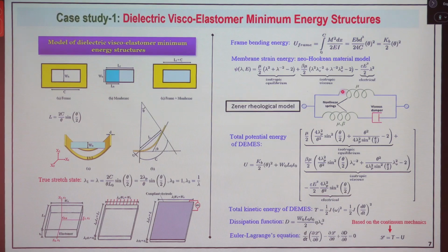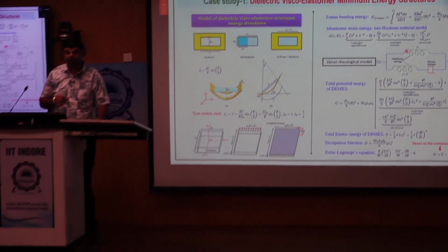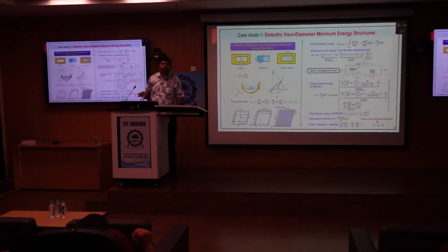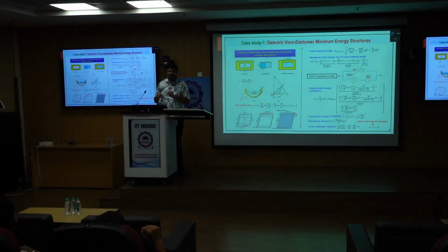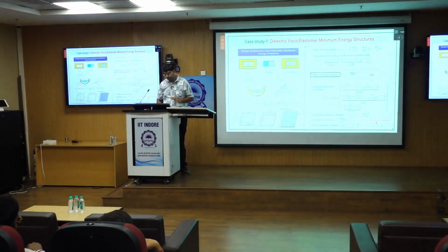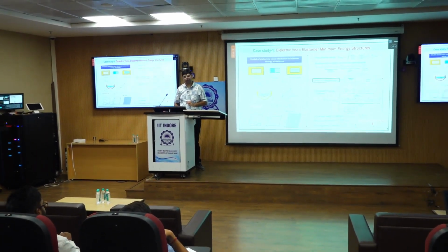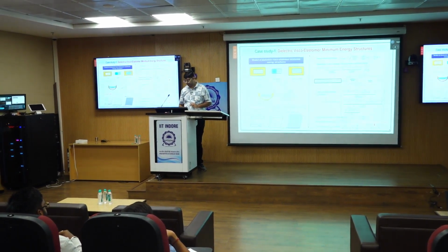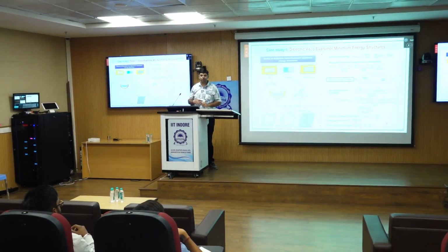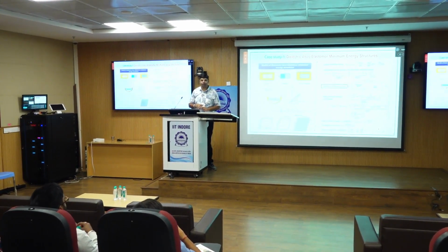Yeah, please. This will be taken care of by that spring. But here this model is only for the membrane. It's nothing to do with the frame. Everything we are talking about is the membrane viscous effect, and this membrane viscous effect is incorporated by using this Jenner model. My concern is why we are going for a hard thing. We can simply use a Maxwell element and incorporate viscoelastic behavior, or the Kelvin-Voigt model, in which the spring and dashpot will be in parallel. You getting my point?